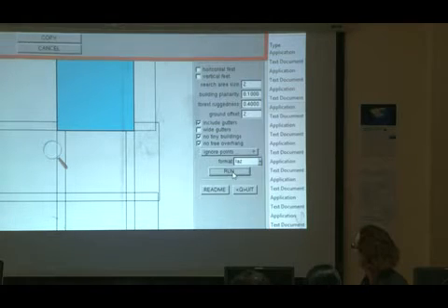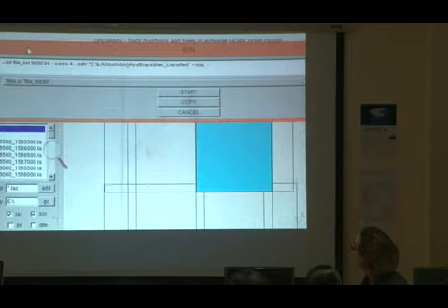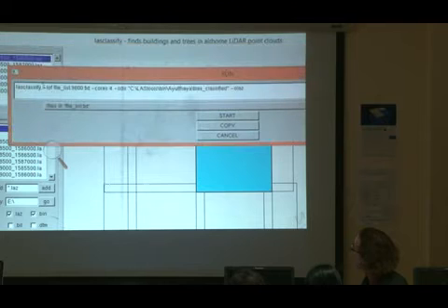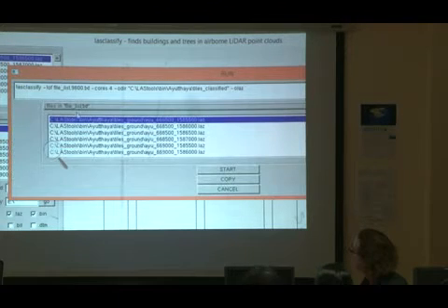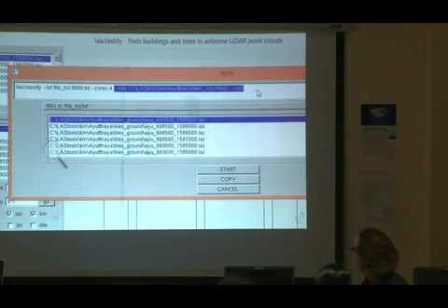So I just loaded the data, I picked an output directory, and I run lasclassify. The data I'm running on is the output from the previous step, the ground classified step. I run on 4 cores, and the only argument is really where to put the data and in which format.